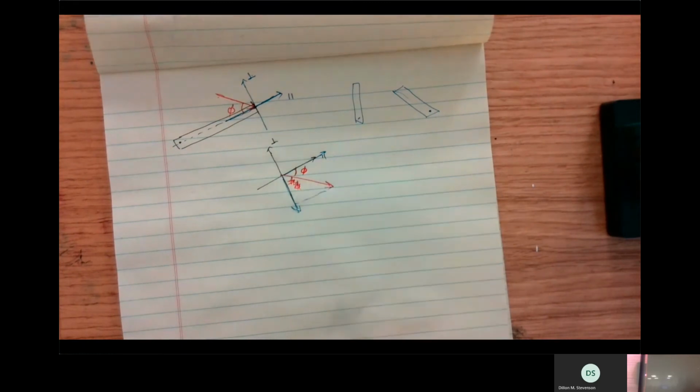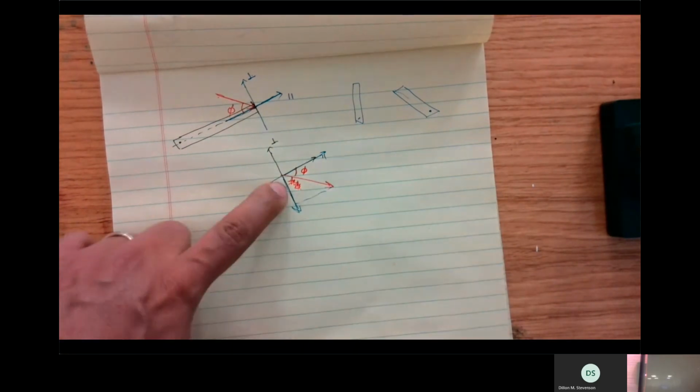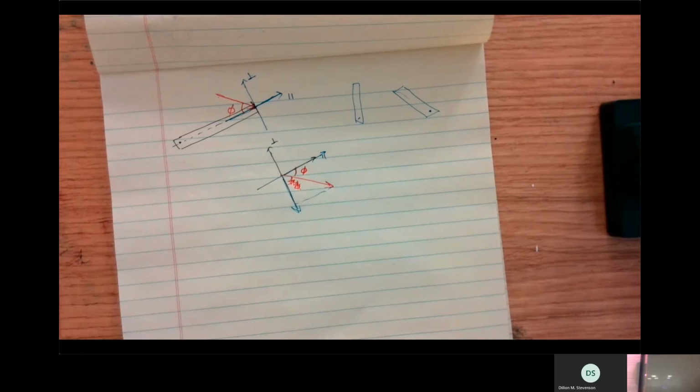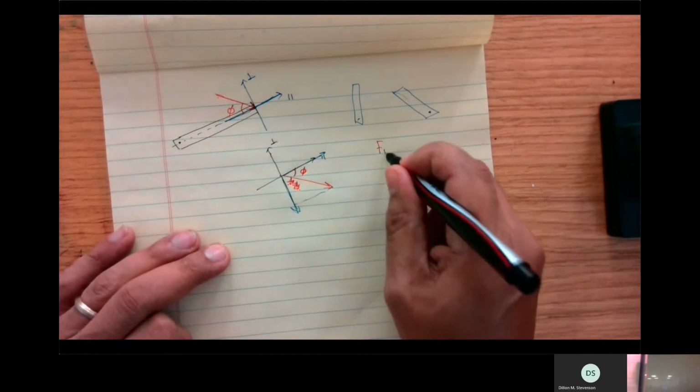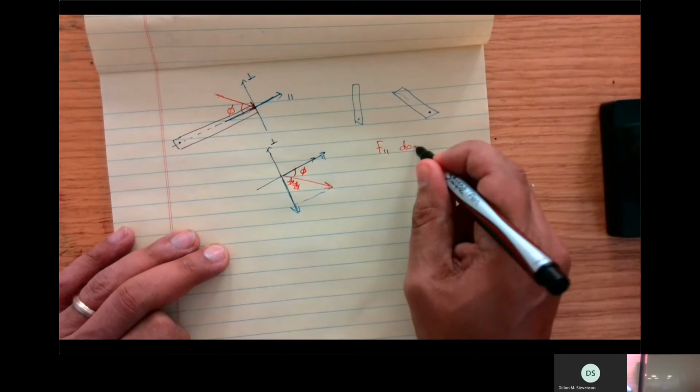Now, the parallel component is going to be along the x-axis. Okay, so imagine that you have your arm extended, and someone is pushing your arm away from you. So that force is not going to rotate your arm with respect to your shoulder. The same way, if you push it forward, it doesn't rotate. It can stabilize your shoulder, or it can dislocate your shoulder, but it's not going to rotate it. So the parallel component of the force doesn't cause any rotation.